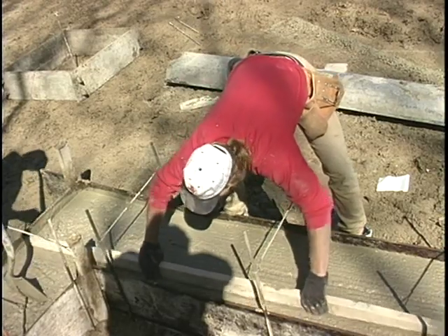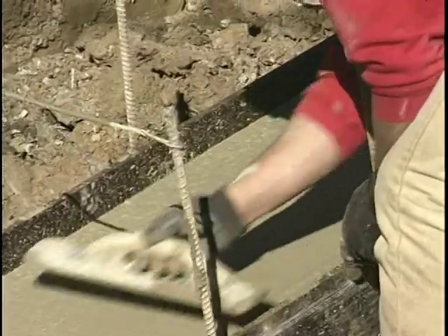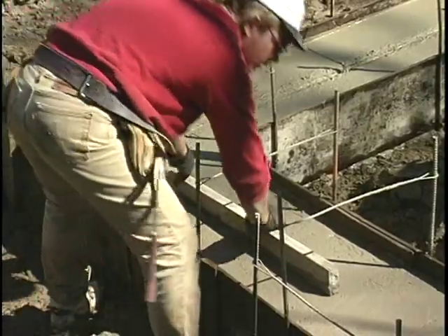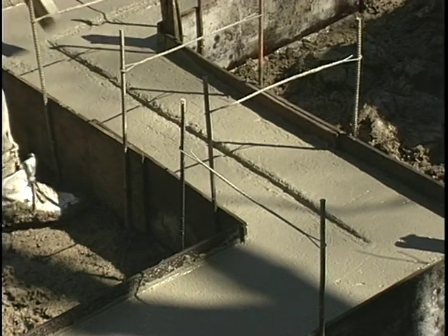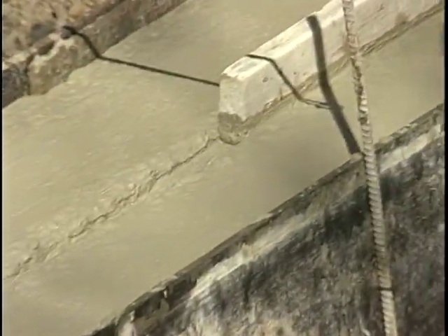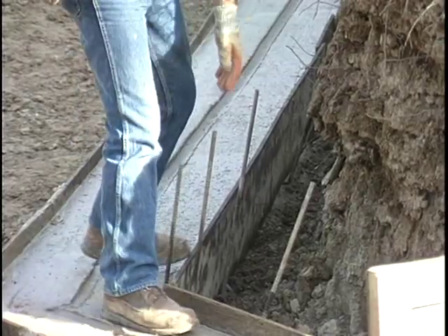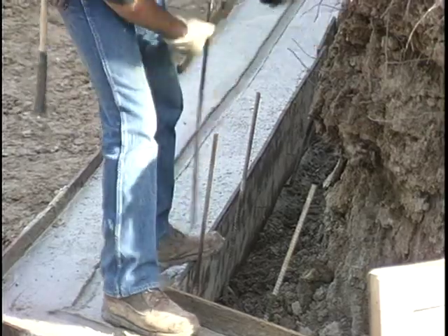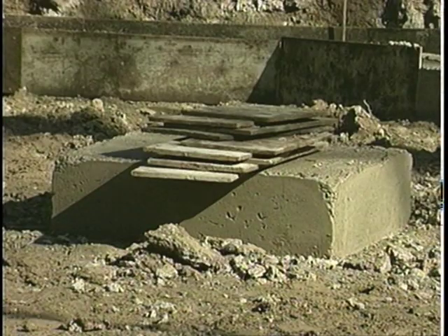Masonry skills are then used to smooth and level the top of the concrete. A piece of 2x4 is commonly used to cut a key in the top of the footer. The key or groove will help hold the foundation wall in place. The poured footer is often allowed to set up overnight. Footing form boards are removed the next day so they will not stick too tightly to the concrete.